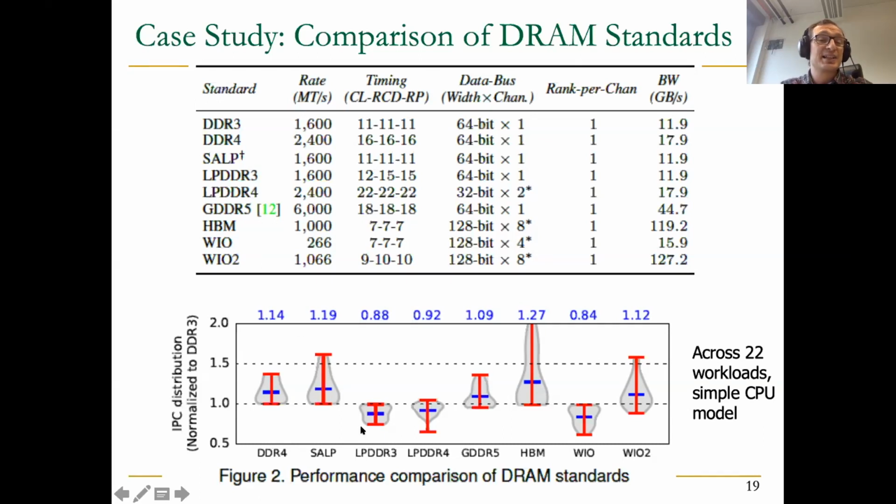And Ramulator is still reasonably cycle accurate actually in the memory part. In the memory part, it models timing parameters. Maybe it doesn't model all of the timing parameters, so that's where the inaccuracy comes in. But for a good chunk of the important timing parameters, they're modeled. As a result, it's reasonably accurate. This also shows that LPDDR3, for example, loses performance, right?